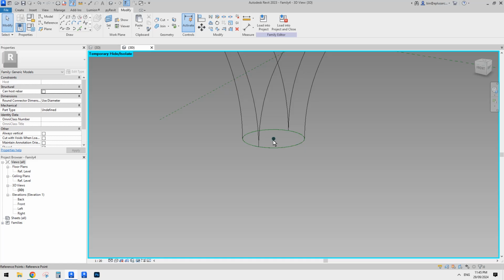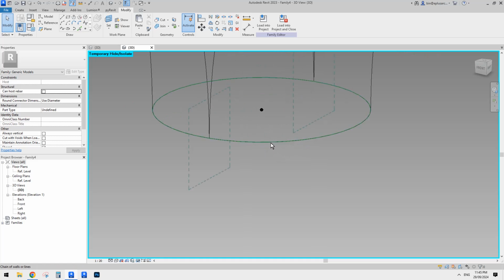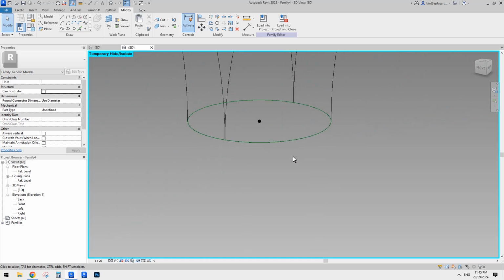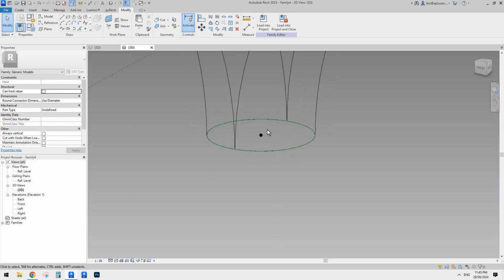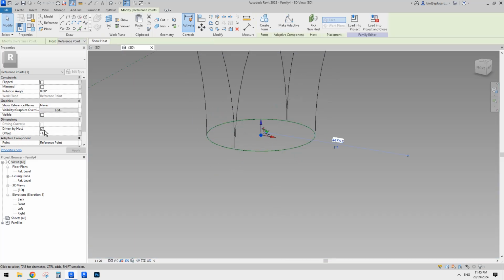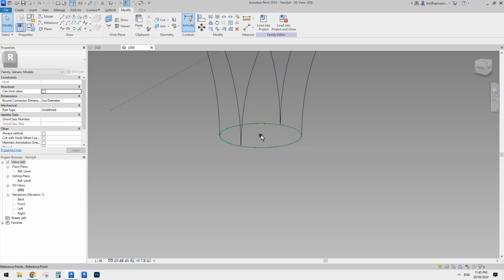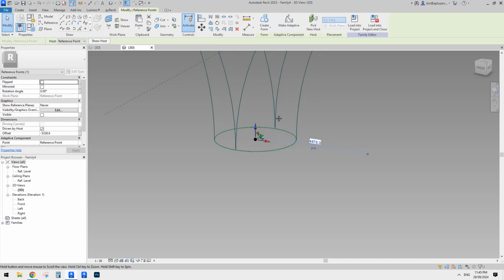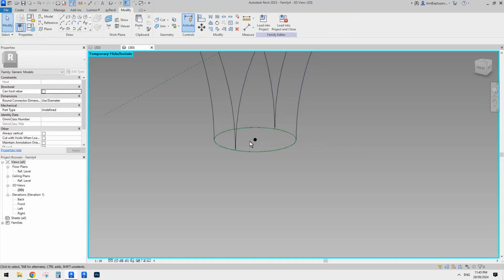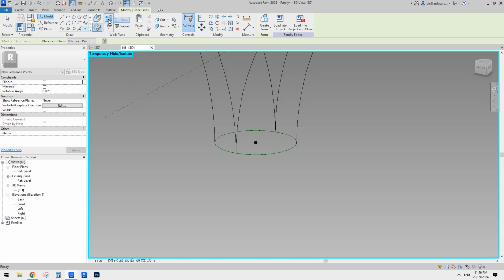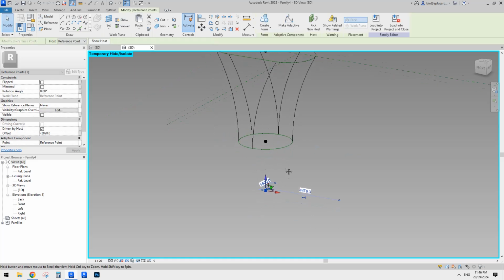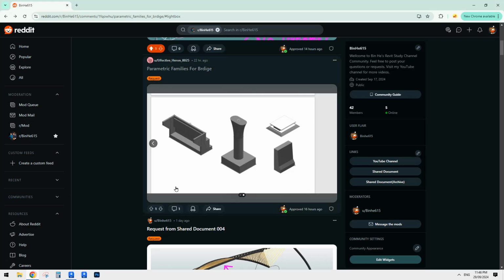We should probably use the one under. So I'm going to type HR to bring back the other point, which is this one, and maybe I'll try to select this one, HH. I'll just temporarily hide it, and then place another point, draw on work plane, set work plane, pick the horizontal work plane of this point, place it on point, and then select this one and offset down. So this will be the height of this part.